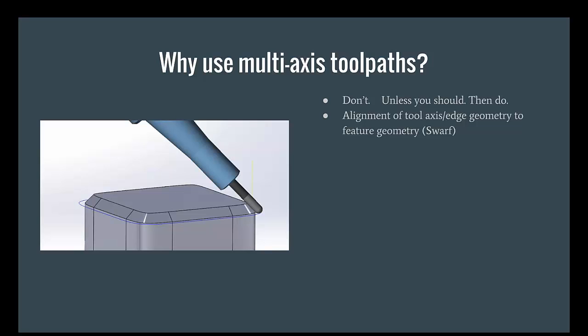It's sort of like if a feature can be aligned perfectly to a tool axis, then this is a great option. Places where you'll see this are, like shown here, a chamfer that sort of wraps around. In this case, you probably would just use a chamfer tool, but if it's at some funky angle or if it's changing in angle, any of that kind of stuff, a 5-axis simultaneous toolpath is versatile. It'll work great. It's a simple toolpath to generate, and most importantly, it's fast on the machine.